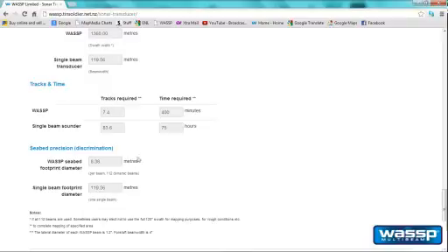However, it will still take 75 hours and 84 tracks to map out that 10 kilometer by 10 kilometer grid with a single beam sounder. And instead of 75 hours, it will take just 400 minutes to do it with the WASSP and 7.4 tracks. So you can see just how much faster, 400 minutes versus 75 hours to search out that area. And this is where a lot of our clients are giving us feedback. They're able to break into new territory faster than they ever had before, and it really makes it viable to go out now and do more hunting and prospecting on unknown territory.